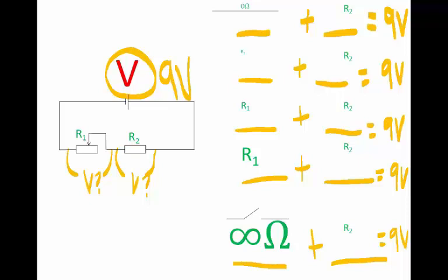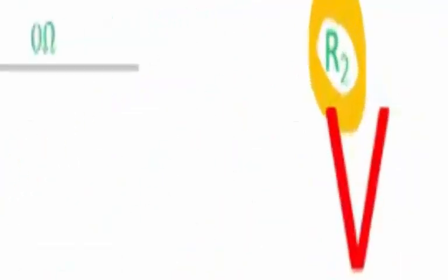How will it differ? Pause the movie while you predict this. When resistor 2 is connected to a good conductor, in other words, 0 ohm resistance, then resistor 2 is the only resistor in the circuit. It will take the full supplied voltage, let's say 9 volt.